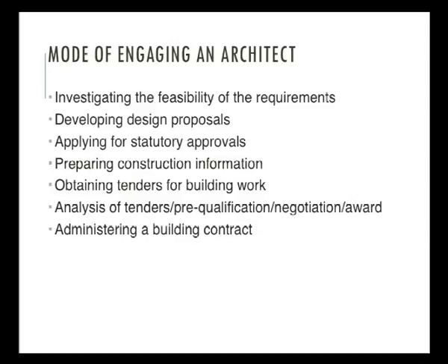Investigating the feasibility of the requirements, developing the design proposals, applying for the statutory approvals, preparing construction information, obtaining tenders for building works, analysis of the tenders, pre-qualifications, negotiations, awards, administering a building contract. This is how an architect can be engaged, and this is how it can be detailed: the appraisals, identification of the client's needs and objectives, business case and the possible constraints on development. So it's like concept making. He should be aware of the request and the client's needs in order to satisfy a concept. So it is important to identify the client's need and objective at this appraisal stage itself.